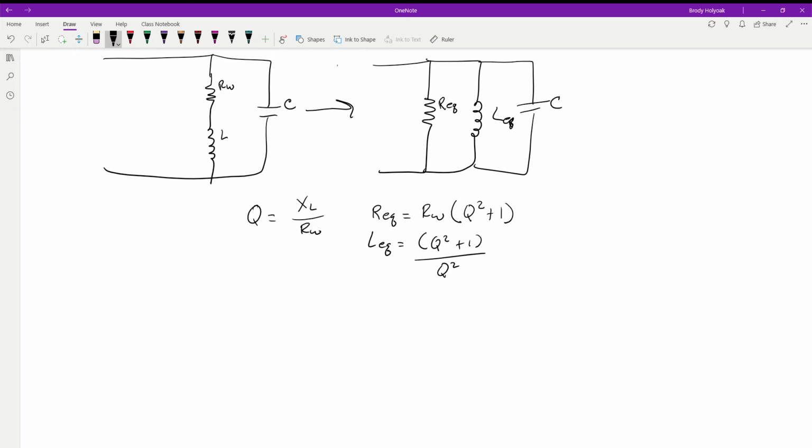And one of the things is that we don't have to take it into consideration when we're doing our calculations later, as long as our Q point is over 10, which most of the time it will be, it's not going to make any difference in the calculations when we go through and solve this. So we're just going to go with it at that. Like I said, most of the time the Q point is going to be over 10. Remember, that's our quality factor. That determines our range of frequencies, things like that. So that's what we have for those equations.